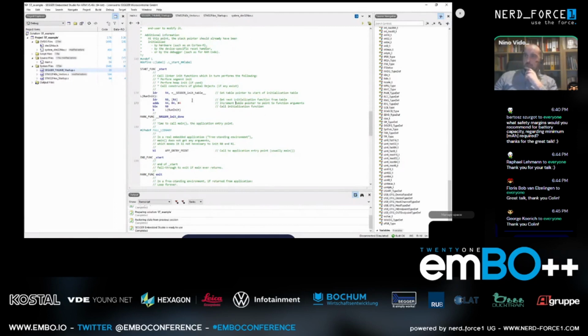But if you take a look here, we let the linker do some optimization already, where the linker dynamically adds the needed initialization functions. Usually at this point you would see, for example, a GCC runtime implementation, a big block of startup code in assembler, which would do all this initialization stuff, for example also the constructor calls for C++ objects.